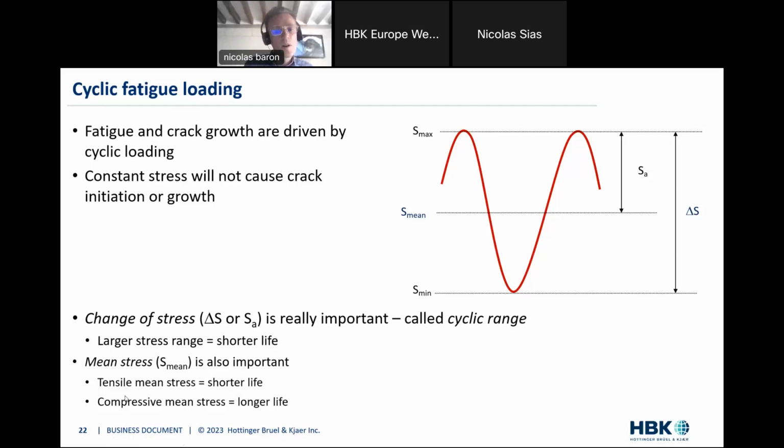On the other hand, when the mean stress is negative, we are dealing with compressive mean stress, and that's good for our designer because, conversely, we're tending to reduce the cracks. So even though the crack might have started, having such a compressive mean stress means in the end we will compress the crack, so they will not grow, they will not extend. So that's beneficial to us. In turn, this leads to longer life.